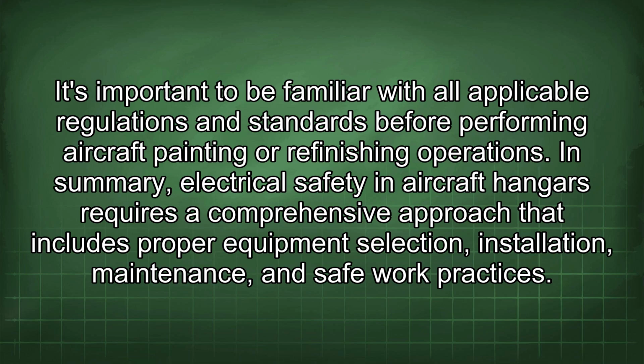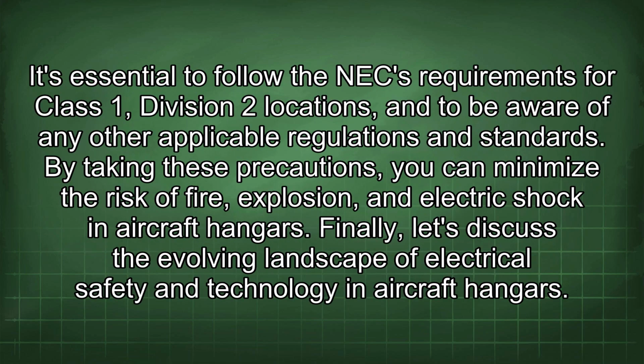In summary, electrical safety in aircraft hangars requires a comprehensive approach that includes proper equipment selection, installation, maintenance, and safe work practices. It's essential to follow the NEC requirements for Class 1, Division 2 locations, and to be aware of any other applicable regulations and standards. By taking these precautions, you can minimize the risk of fire, explosion, and electric shock in aircraft hangars.